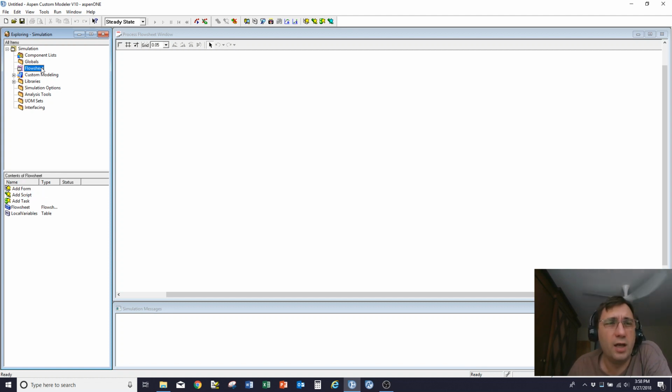The flowsheet level contains a listing of all the items on the flowsheet, plus any information that is specific to the whole flowsheet. So, for example, if you put in equations for the economics of the process, you'd put those into the flowsheet level. If you build summary graphs or summary tables of data, those would probably be flowsheet level pieces of information. And this will make more sense once we get into some examples later.